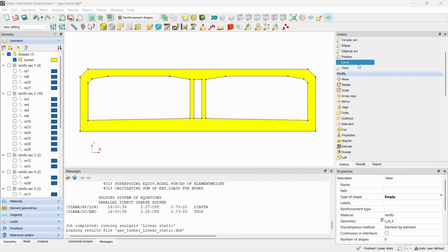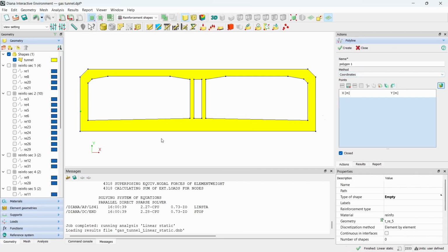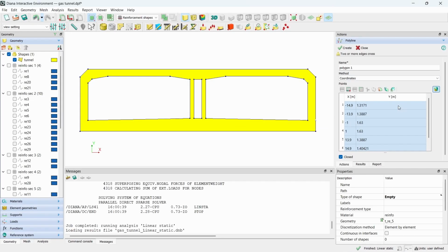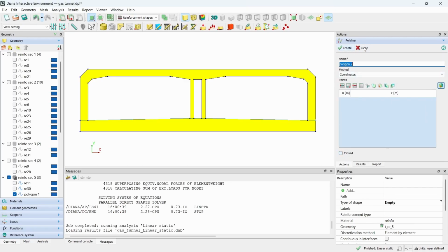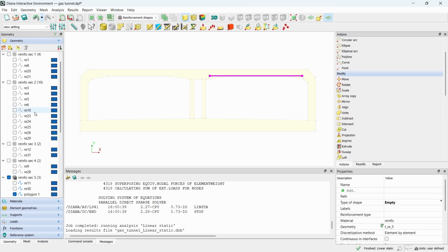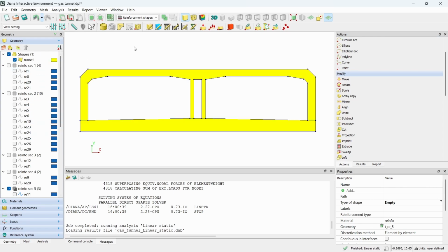So before we conduct the eigenvalue analysis and the transient and linear analysis for the explosion, we first would like to reduce the geometry to save some computational time. The justification of this application is that because we consider the bottom of the tunnel is connected to the ground, it is relatively rigid.